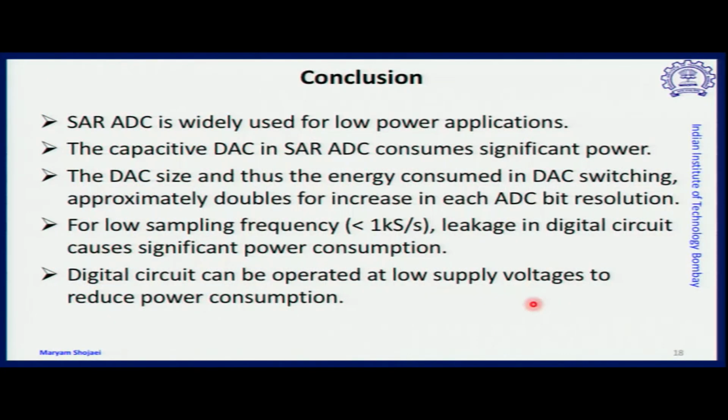For low sampling frequencies, even leakage, the static power of the digital circuits, contributes to the power dissipation. And finally, to reduce the dynamic power, we can operate digital circuits at low supply voltage, which is the common trend in recently reported systems on chips for IoT applications.